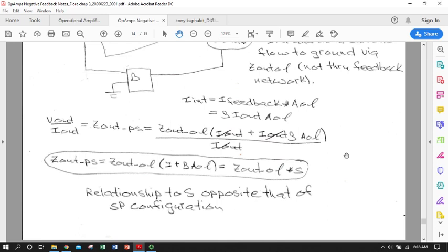If you go back to early chapter 2 and chapter 1, the objectives of amplification, we want to preserve our signal, minimize our losses. So if we're looking at a voltage gain, we want high input impedance, low output impedance. Current gain, it's the inverse.